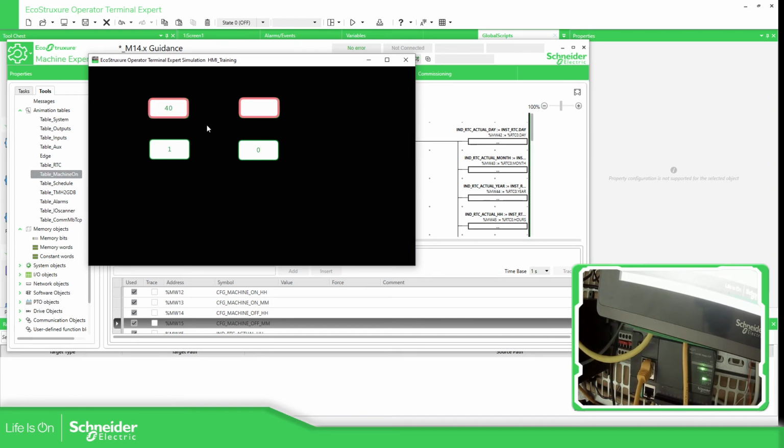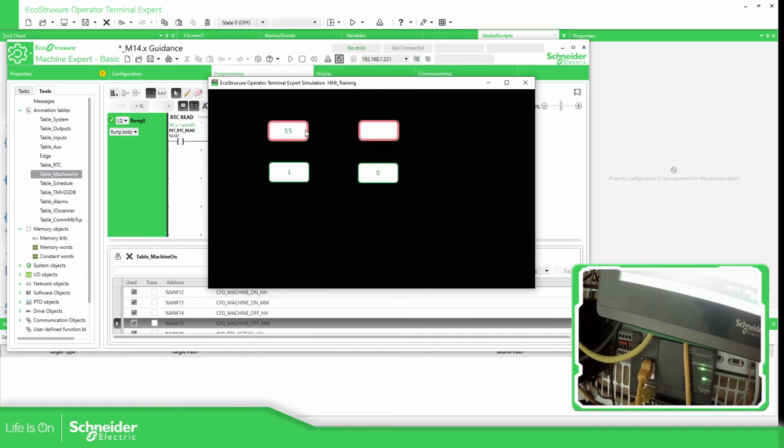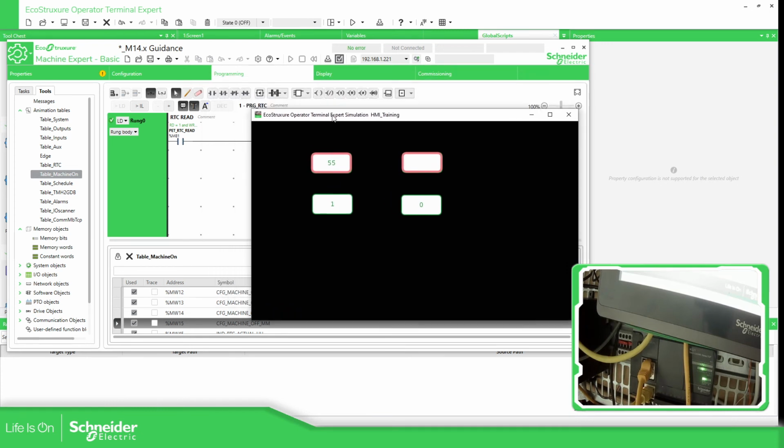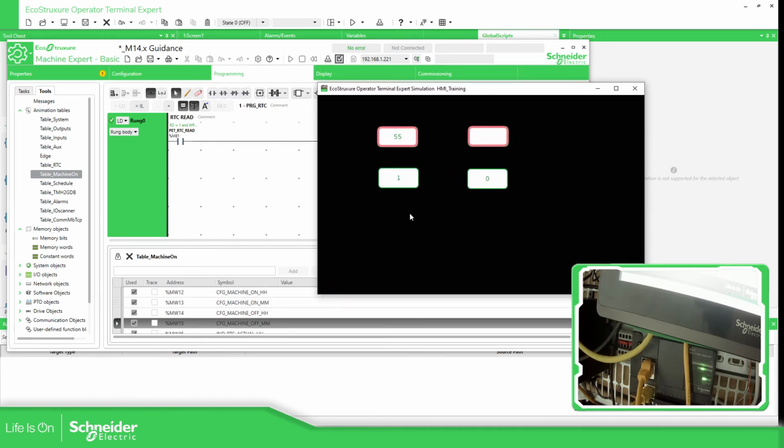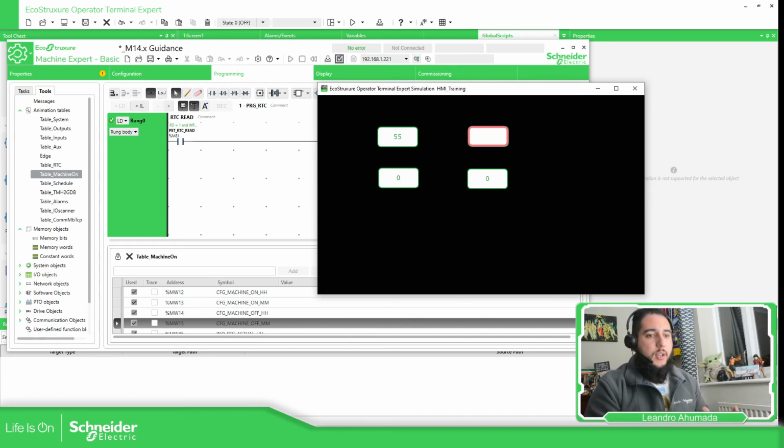Okay, so you can see there's a red square. Now, if I connect again, which was the cable, this one. If I connect again, the Ethernet port, this one we should change. Okay, value change. Should be able to change this value, otherwise I haven't done something different. There we go. So you have the communication again. Okay, it changed. So using the quality of the variable allows you to define if you have communication or not with the device.